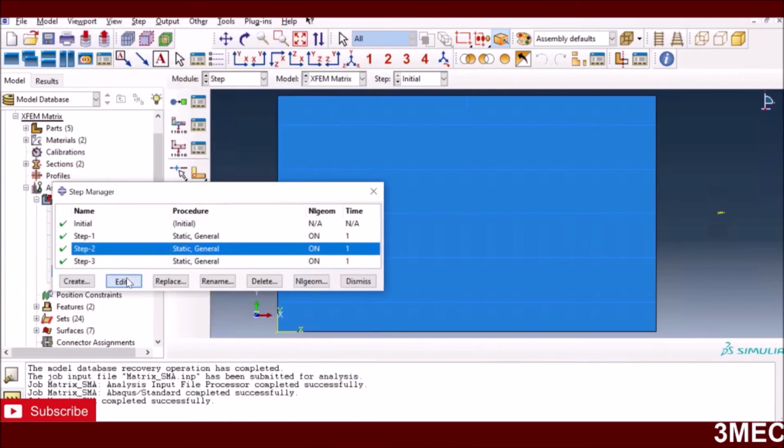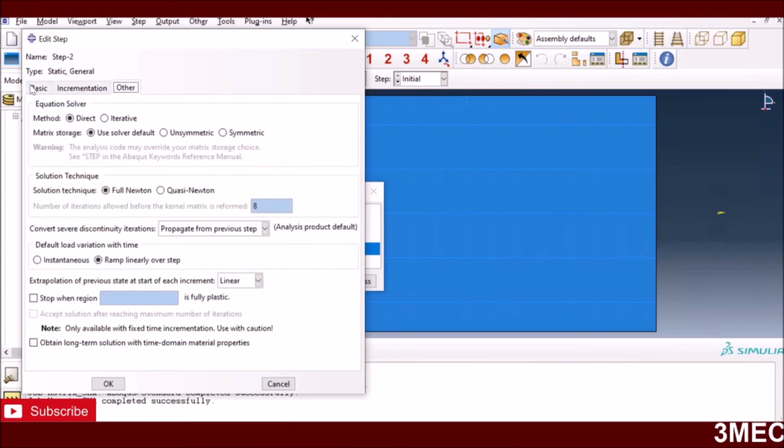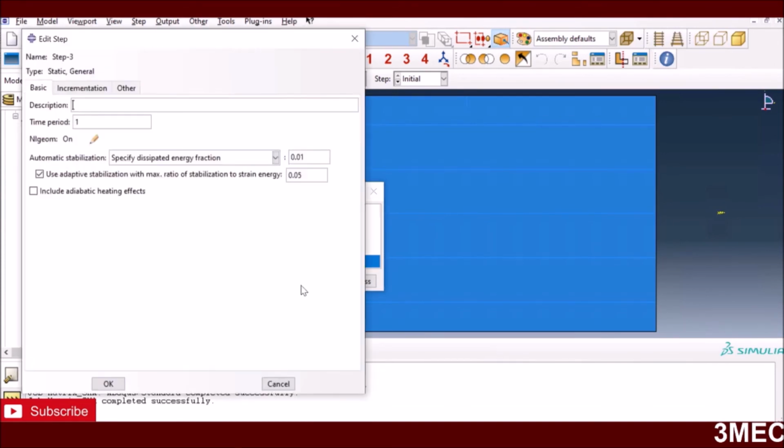The second step is not necessary for you guys, but I normally do it after this kind of loading. I want everything to stabilize, so I just stop everything at that point where it stopped in the last step, and I let it run without any changes, so that all the matrices are computed and everything is stabilized. So again, parameters are the same as before, and I'm not changing anything. This is not required in my opinion, but you can avoid that. And the third one is basically the unloading step, where I remove the displacement boundary condition loading, and then it will start to relax as was done in the paper.